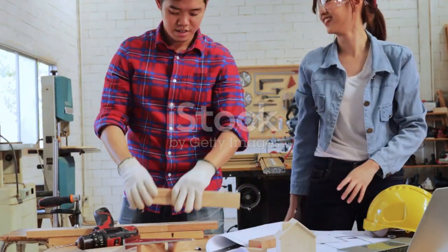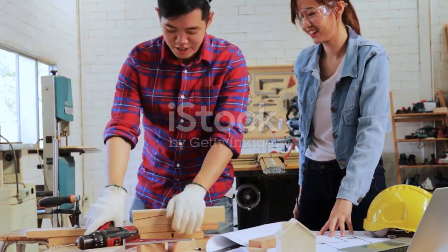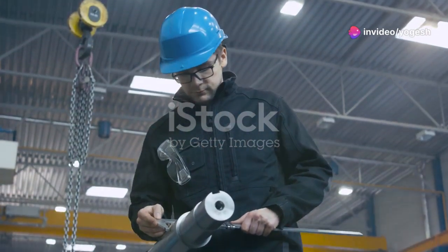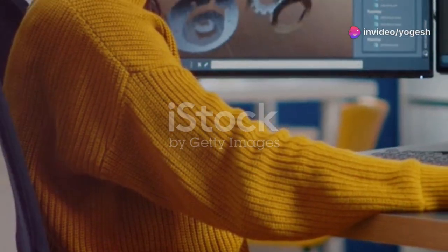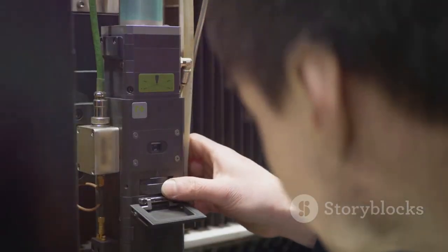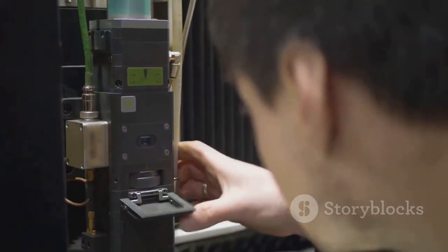Here's the most important advice. Talk to your toolmaker. They know what works for their machines and materials. Before finalizing your design, get their feedback on draft angles. Sometimes a small tweak makes all the difference.